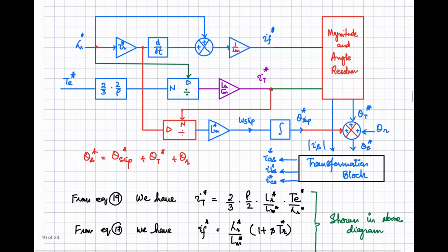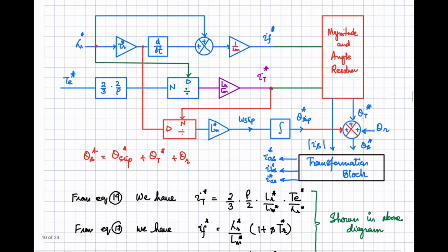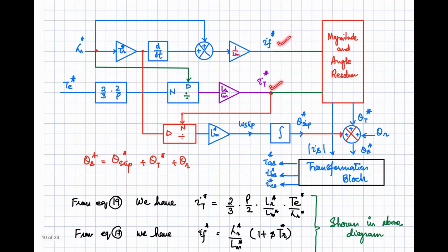These parameters are used over here that you can see, and which are extracted from these two commands and are used to set up the reference currents for the inverter control. These currents are given to the inverter control, and the inverter realizes these currents in the induction motor.